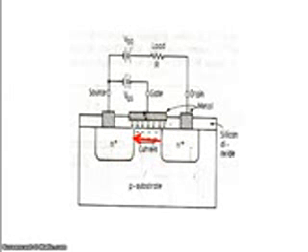And now if VGS is made more positive, the induced N channel becomes deeper, and therefore more current flows from the drain to source. So this shows that the drain current ID is enhanced by the gradual increment of VGS. Hence this MOSFET is termed an enhancement MOSFET.